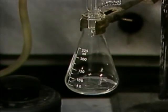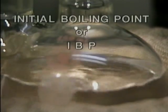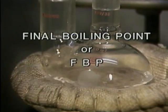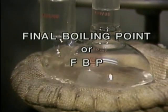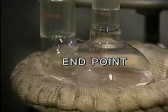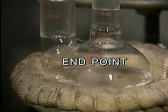Then, to recover the separated substance, the vapor is changed back to a liquid. The boiling point of the component in the mixture that boils at the lowest temperature is the mixture's initial boiling point, or IBP. The mixture's final boiling point, or FBP, is the temperature at which the component that has the highest boiling point boils. The final boiling point is also commonly referred to as the end point of the mixture. The end point is the end of the mixture's boiling range.